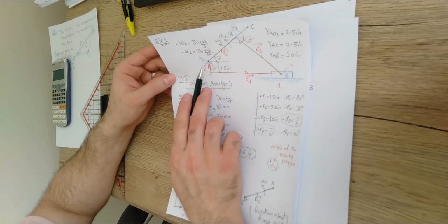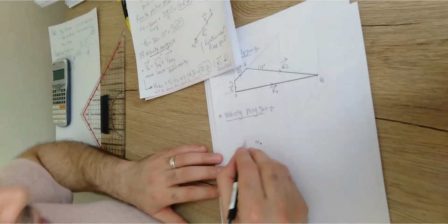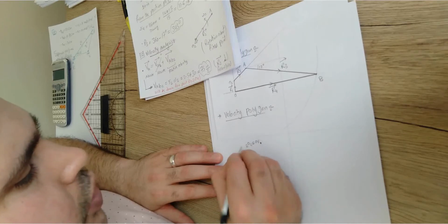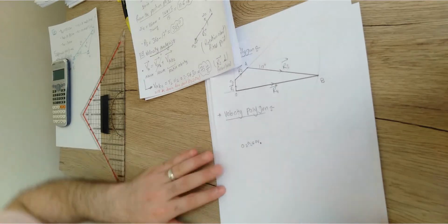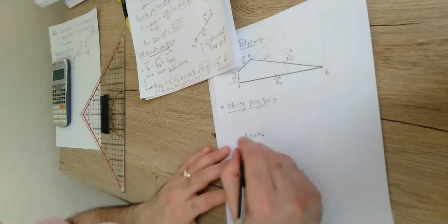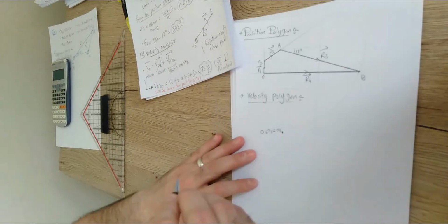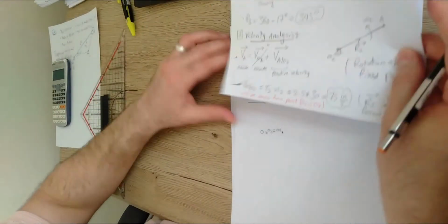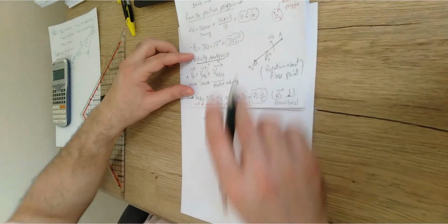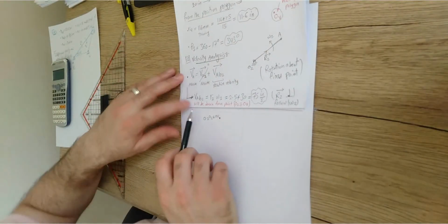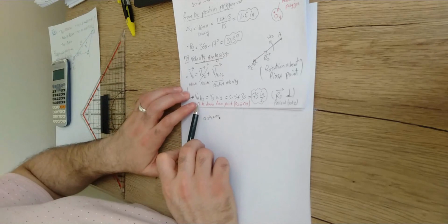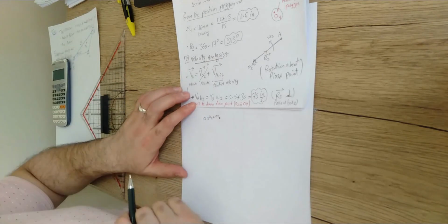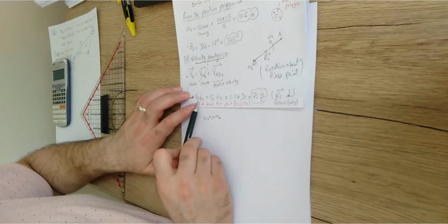It means that point O2 and O should be coincident over this point. This point is O2, and the same point is also point O. So the points should be located over the same point OV. This is the start point. Make sense? If we return to the plan here, the first relative velocity, or the first vector that I have to draw, is VA relative to O2.